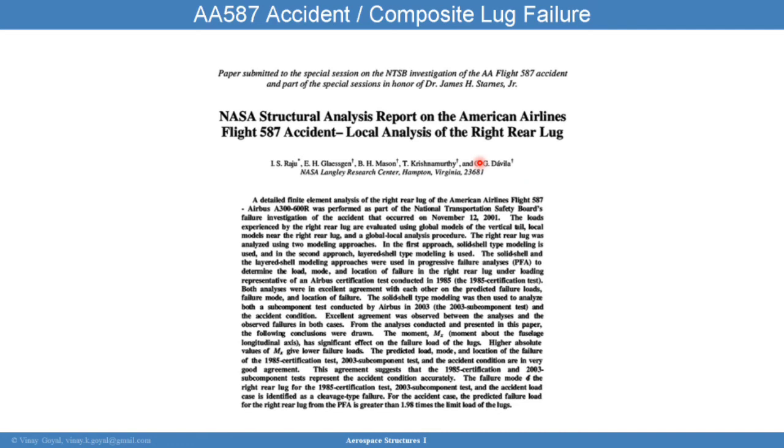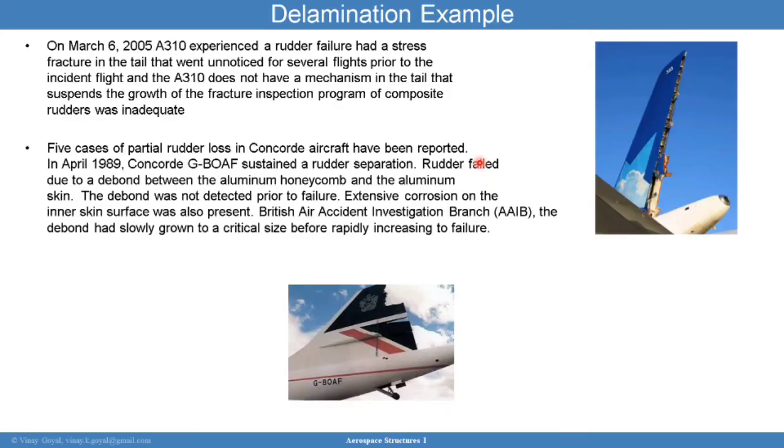From the analysis, they concluded that the modeling is capable of predicting the cleavage type failure modes that we're seeing, and that the loads applied during the failure event were 2 times the limit load of the lugs, as described in the accident report.